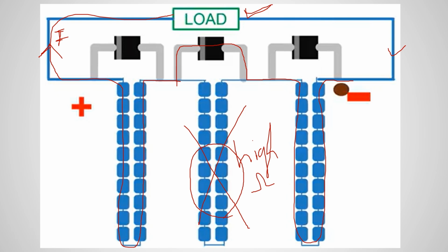It becomes forward biased because the current is coming here and goes through the diode. And simply you can remember this current is going to go through the diode because the diode has less resistance compared to the shaded cells. So here we are separating some number of cells into sections, like 3 sections, and we are connecting 3 diodes. You can separate into multiple sections and have multiple diodes. It's up to the designer's perspective.